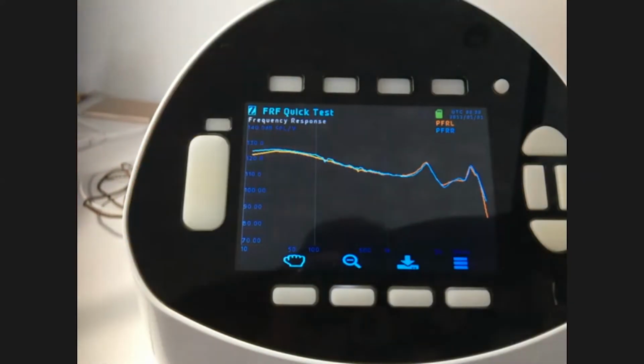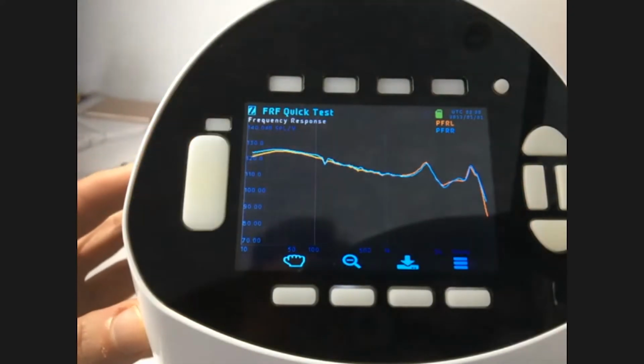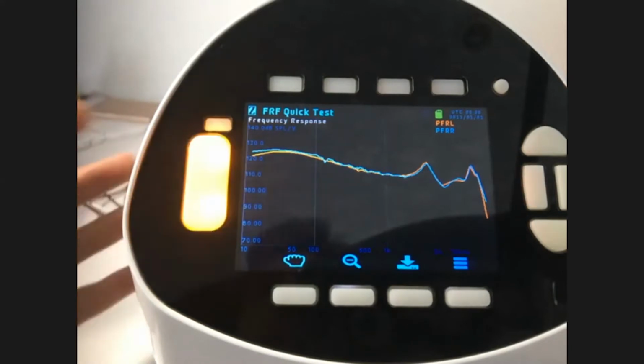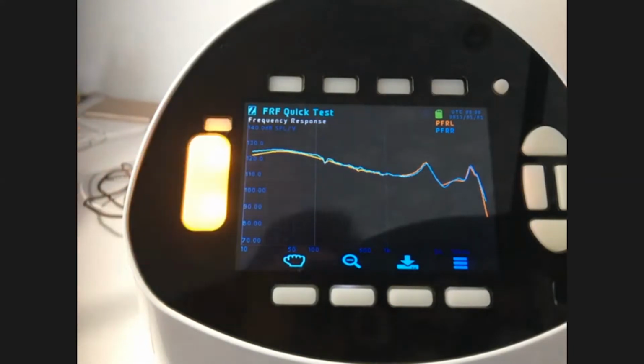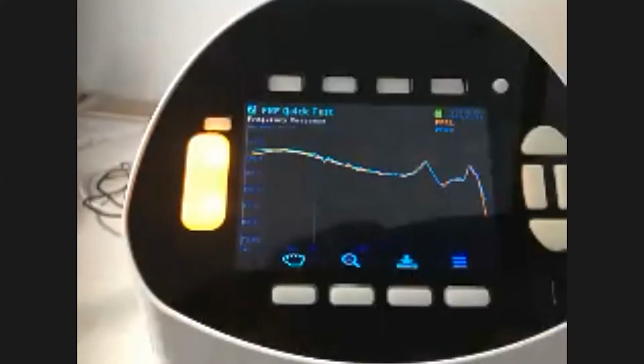We'll have a look at some big over-the-ear headphones shortly and see that doesn't stay the same for over-the-ear headphones. But in these insert earphones, the total acoustic volume is so small that there's no standing wave frequency. So you've got almost an ideal pistonic system, essentially, right up to the high frequencies.